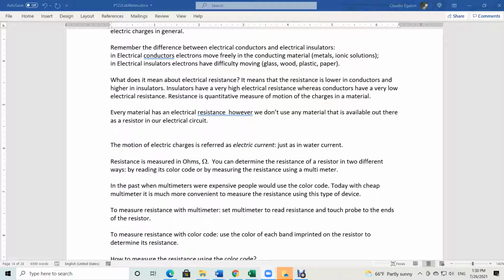So here you go. Right now the probes are measuring the resistance between those 2 points, between the black and red point, and you have this funny number 1 in there. It's not exactly 1 ohm. And notice also that I have set my dial to measure resistance, ohms. I can put in any scale I want, and it's still displaying that funny number 1. The number 1 is to the left. And this number 1 in this multimeter means a very high resistance. That's what it means.